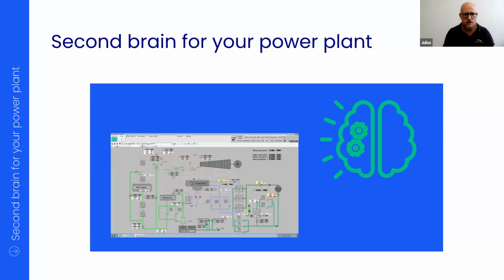You have the control system and it makes the plant work well enough and not burn up. But the digital twin takes it to a new level by controlling the set points instead of the operators. So the set points are no longer influenced by human factors like experience and knowledge. Of course, the digital twin works within the zones set by the commissioning engineers, but it's still changed much more quickly than by the hands of the operators.